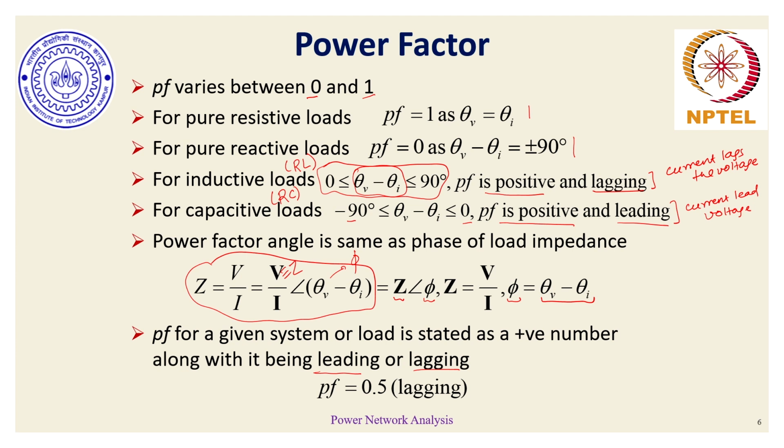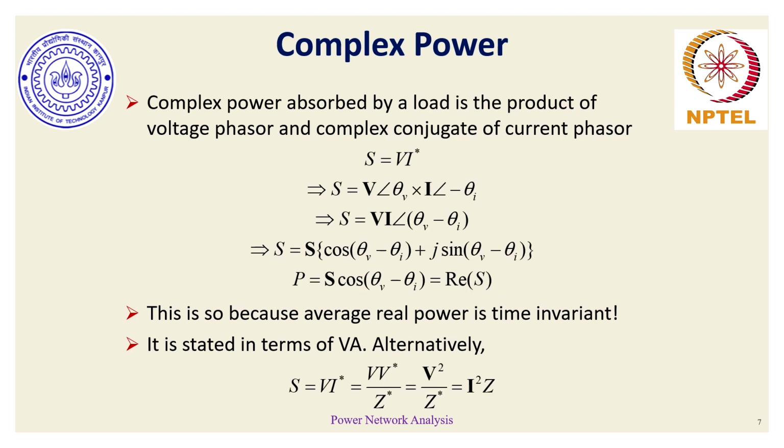factor, if the power factor value is different from 1, and theoretically the power factor can go till a value of 0, any number of power factor between 1 and 0 would always have this notion of lead or lag associated to it. If power factor is equal to 1, it implies that the corresponding element behaves as a pure resistor, and in a resistance the phase angle difference between voltage and current is 0. So there is no need of having this notion of lead or lag when power factor is equal to 1.